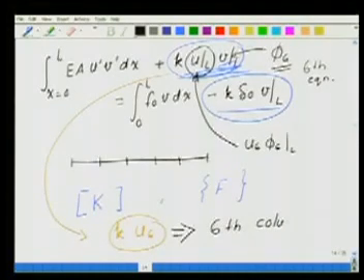So in the stiffness matrix that we have obtained out of our assembly, we go and add k, because U6 stays in the displacement vector. So I will add k in the 6th column of the 6th equation. So that is the first thing we have to do.